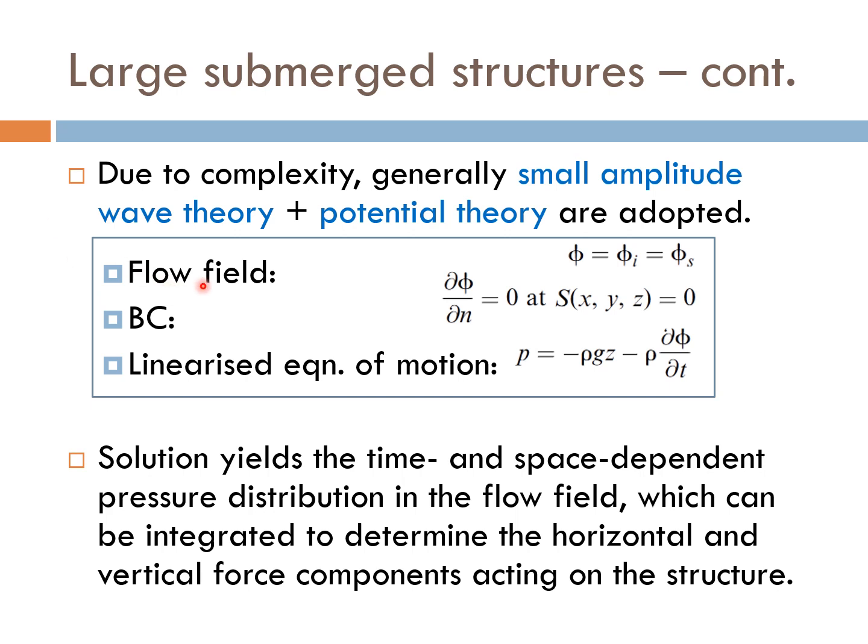Here the governing equation for the flow field, the boundary conditions, and the linearized equations of motion look like this. We will not go into further detail on this particular subtopic. Suffice it to mention that by solving this equation, we should be able to get the time and space dependent pressure distribution of the flow field, which can then be integrated to determine the forces acting on the structure.